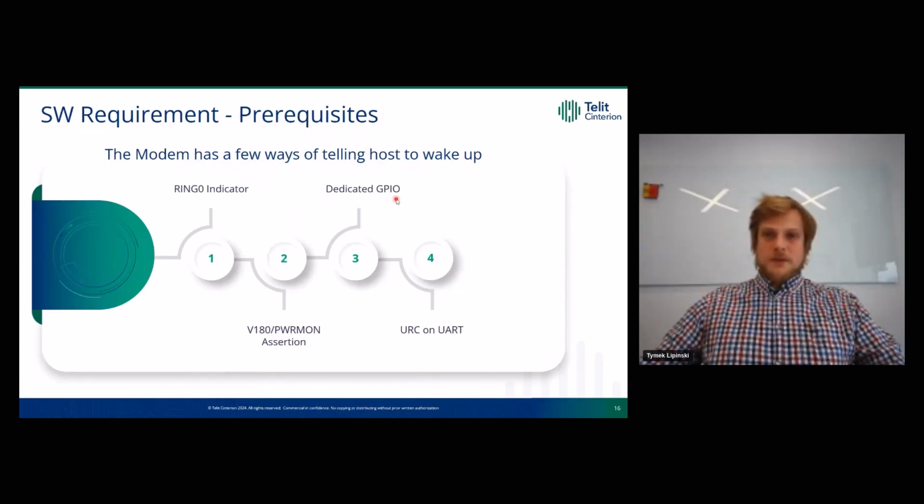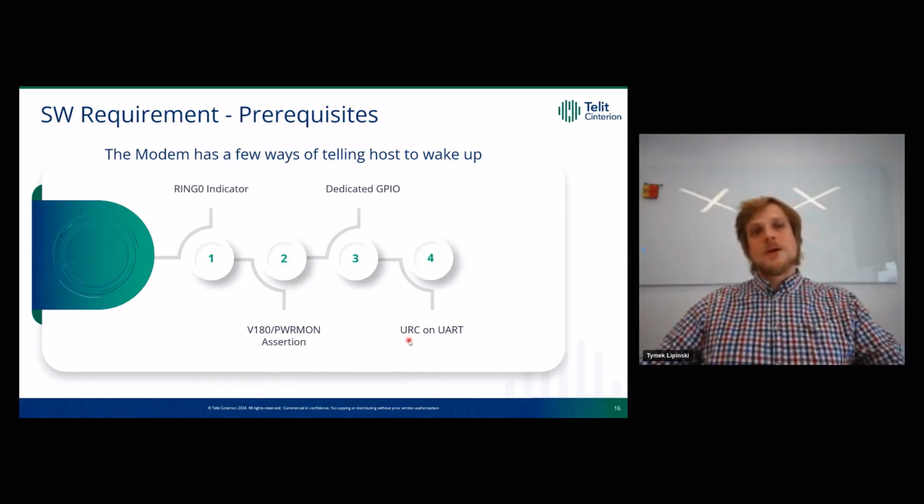In some of our products, we can configure a dedicated GPIO that will toggle when the module wakes up. And for some simplified application where the MCU or SoC is capable, we can have URC on UART. URC stands for Unsolicited Result Code. So when the modem switches back on, it simply sends a short message on the serial interface to the host, and this can be used as a wake-up trigger for the whole system.